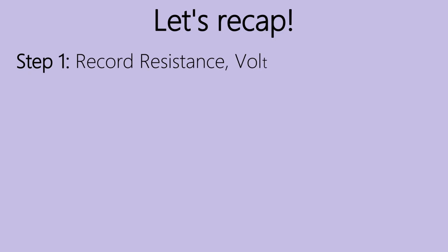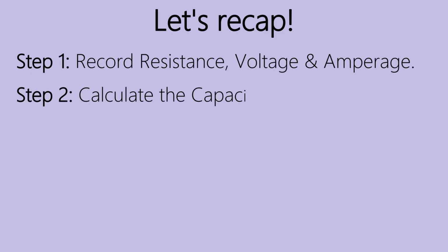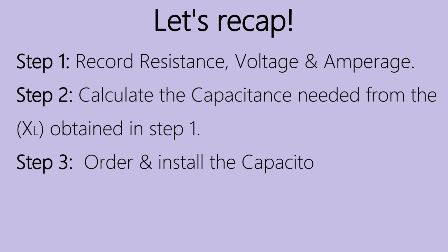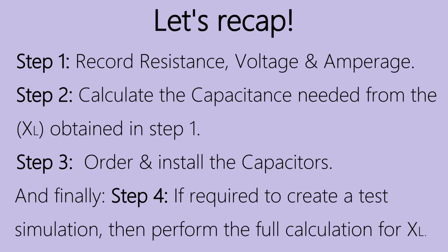Let's recap. Step 1. Record resistance, voltage, and amperage. Step 2. Calculate the capacitance needed from the XL obtained in Step 1. Step 3. Order and install the capacitors. And finally, Step 4. If required to create a test simulation, then perform the full calculation for XL.